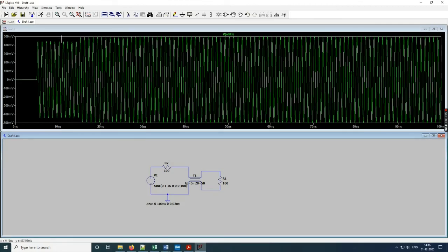Now you see that obviously there are some ups and downs in the load voltage, but it is different from what it was before, because now we have introduced a source resistance. The first time the reflected wave goes back to the source, it will again undergo a reflection with a reflection coefficient of 1 by 3. That will keep getting added up, and the resultant voltage magnitude will be roughly about 500 millivolts, which you see is exactly equal to half of the amplitude of the input voltage.